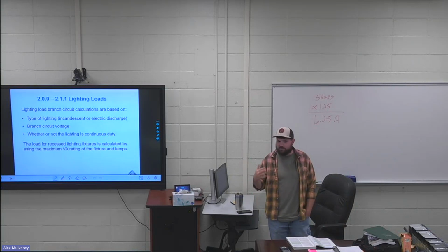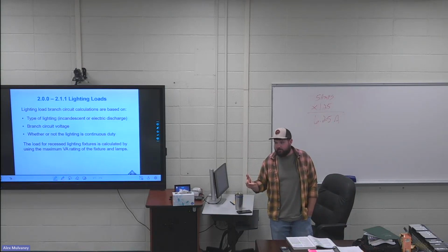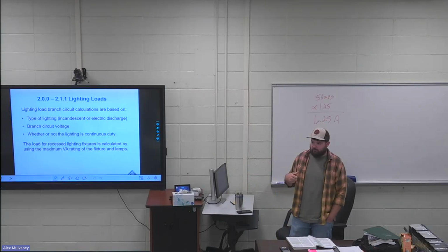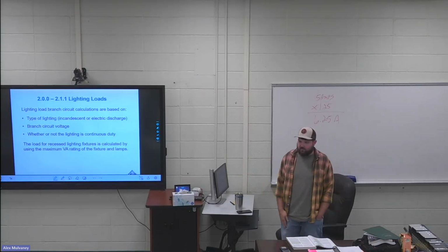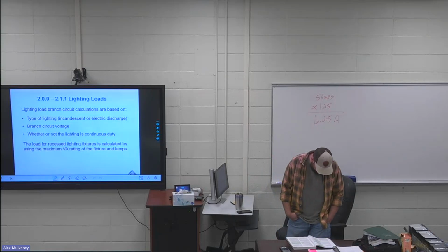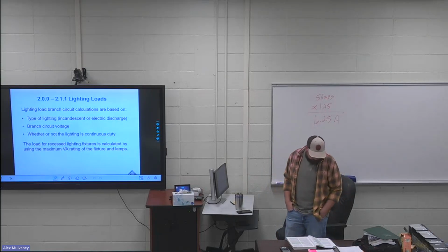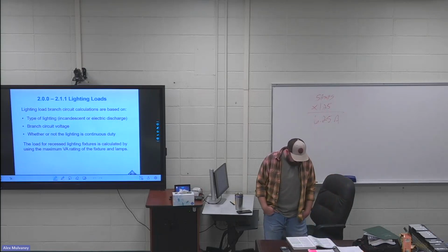And like everybody knows, these are multiple choice. They don't care if you got every single part of the question right and then forgot to multiply by your continuous load, and they're going to give you both answers. All right. So make sure you hit it whenever you see that this load is going to be used for 3 hours or more.